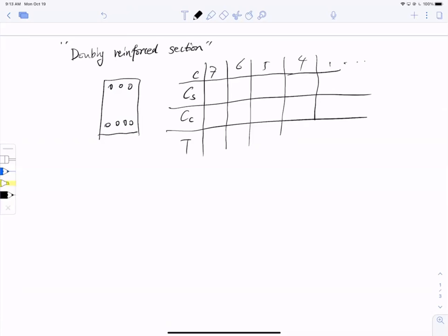To get the compression force from steel, that's fine, but you don't have to show it, just for your own sake. All I wanted to see at the end of this table is that you reach CS plus CC equal to T. Now, we said 5% tolerance, 3 to 5%. I think the best, let's keep it below 3%. If you hit 5% on your exam, I accept that, which is fine, but let's get a tighter control on 3%.